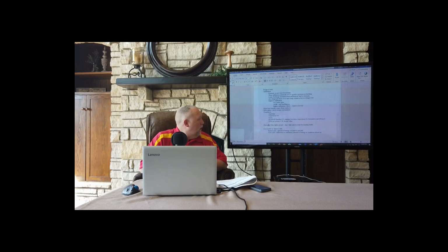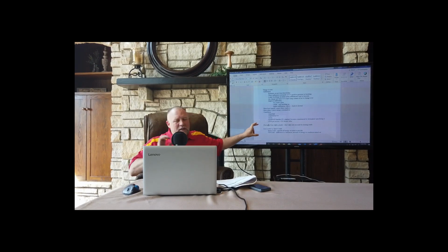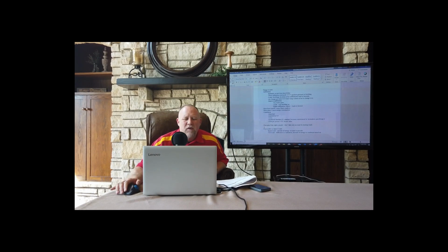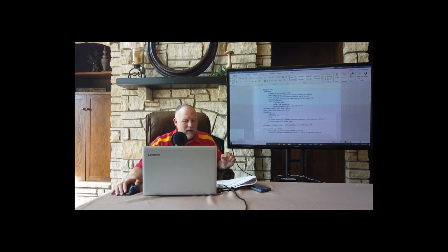All right. Notice we didn't talk about heat from lights and people. We do not take them into account for heating loads. We are definitely going to take them into account for cooling loads. Lights and people warm the space up, but we don't take credit for them.